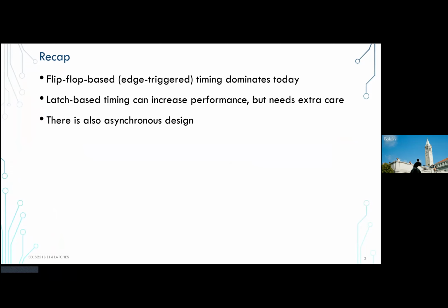But the way we broke it up was by comparing the amount of logic that is allotted to a particular cycle to the actual cycle in latch-based timing, and figured out if we are borrowing or passing some slack. That's the way we can do this timing analysis from a cycle to a cycle.